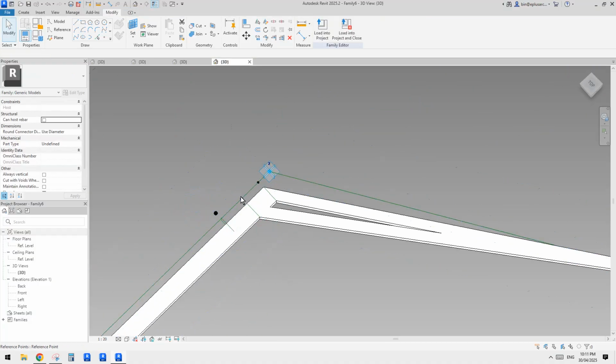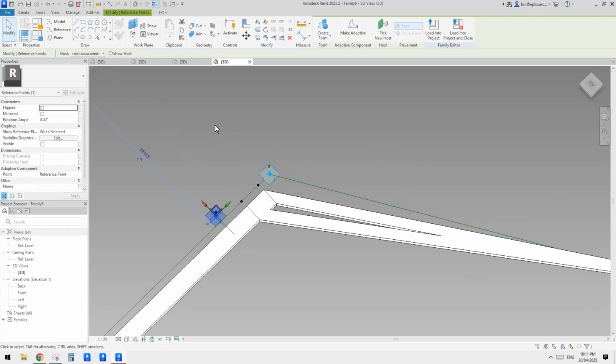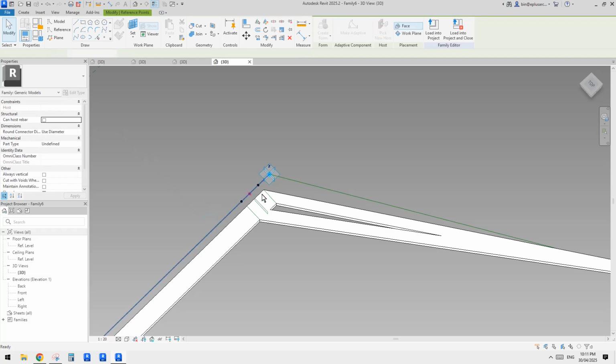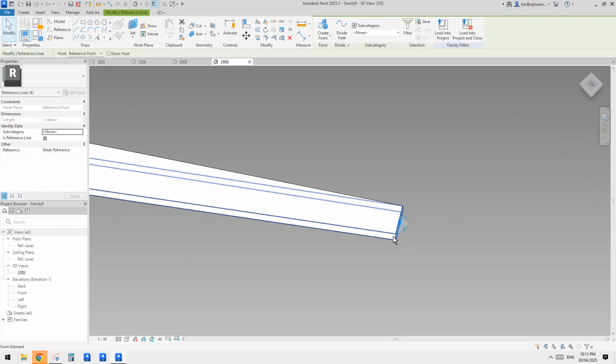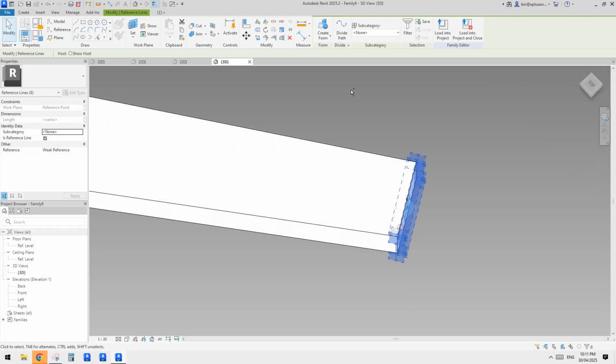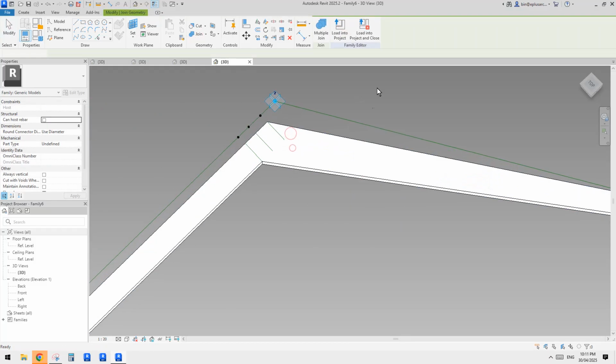So this one is 200, right? So 200, 500. How about we just place another one in the middle? So flip around, section length 350. So select this profile, and also select this one, control select, create a form. So now we have something in the middle. So now we can join geometry, that's it.